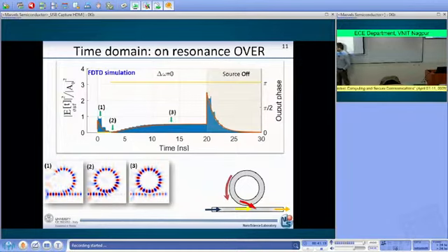So between here and there, you have a phase difference. The phase difference is caused by the fact that the light that you get here is not the light that was entered, but the light that was traveling inside the microring resonator and was exiting from it. And therefore, while traveling within the microring resonator, it has accumulated phase. And this is the reason why you observe this phase difference.